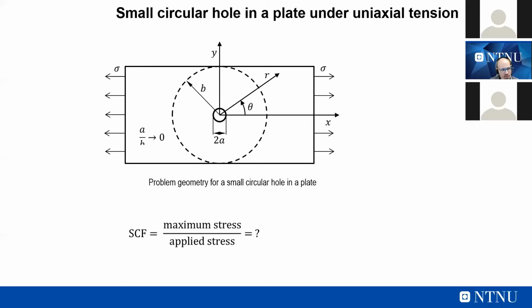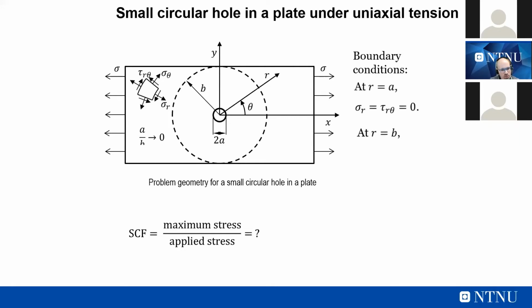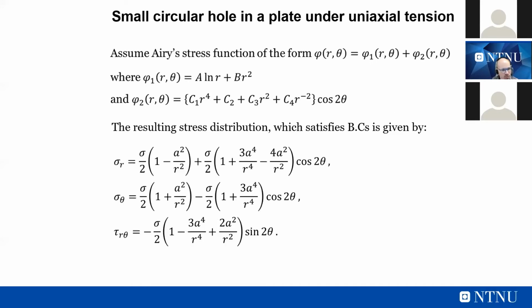So the question that Timoshenko and the other researchers wanted to answer is which is the stress amplification, or stress concentration factor, that you have due to the notch close to the notch tip. Timoshenko put some boundary conditions that I don't want to describe here in detail, but it is mainly due to the fact that you have a free edge on the notch, so you can put the stress equal to 0 on the edge of the notch, and you can impose this equation easily. And after that, you can impose the so-called Airy stress function, from which you can derive the stress field distribution of the notch.